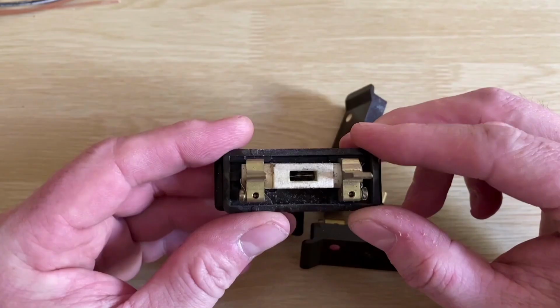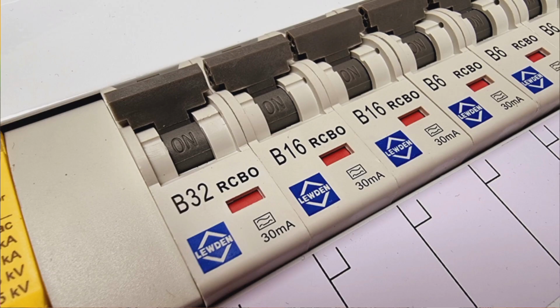to very dangerous consequences. But surely our fuse, circuit breaker or RCD will detect and disconnect this? Well, unfortunately not. The fuse or circuit breaker will operate when too much current flows, but in the event of an arc fault, there isn't an excessive amount of current flowing. It can be a relatively small amount, but the danger now arises from the arc causing damage, not heat caused by the current in the conductor.